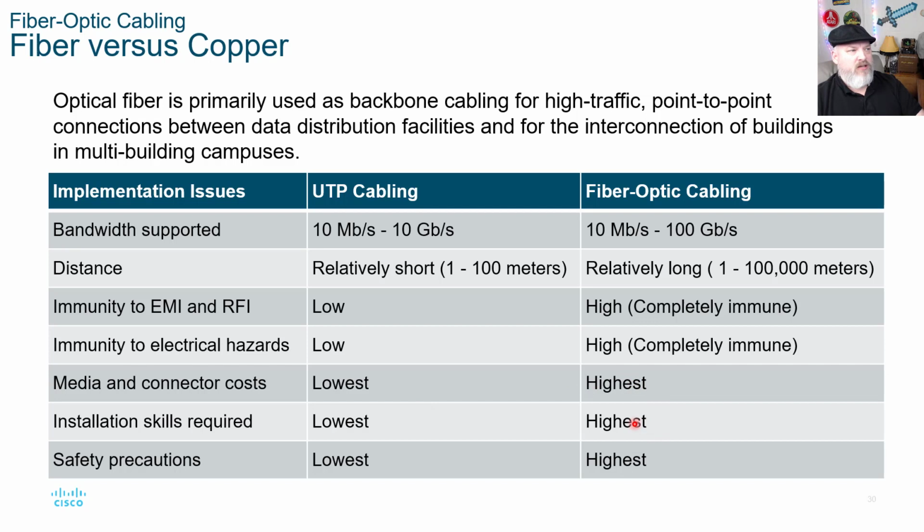It's going to be expensive. The installation skills required take a lot to learn how to do fiber, and the safety precautions matter. You have to be really careful because if you bend the fiber wire too much, it'll snap the glass. It's much more delicate than copper.